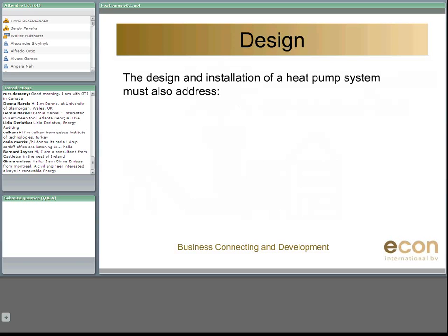And I think air is available everywhere in the world, so it has a lower investment cost. But please note that an incorrect installation of your heat pump will also give you higher electricity bills, poor indoor comfort, and perhaps some maintenance problems. Incorrect airflow across the indoor coil is a common problem in air source heat pump installations, and a lower airflow will affect your cooling and heating capacity, and finally, of course, also the efficiency of the unit.